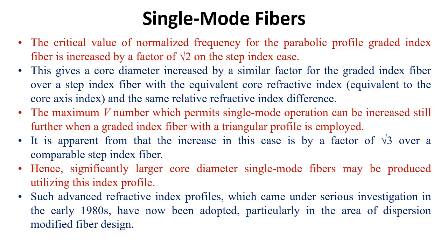Still further, when a graded index fiber with a triangular profile is employed, depending on the application, you can change the profile. That alpha value of the index can be manipulated to get the advantages of that particular design. It is apparent that the increase in this case is by a factor of √3 over a comparable step index fiber. Hence, significantly large core diameter single mode fibers may be produced utilizing this index profile.